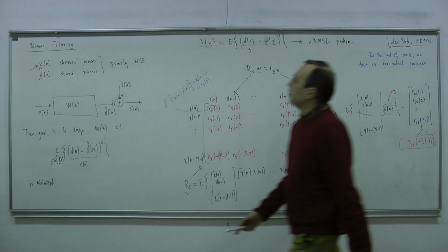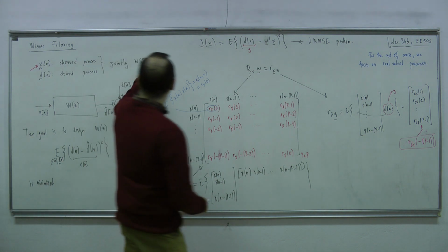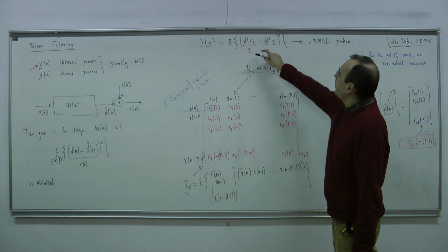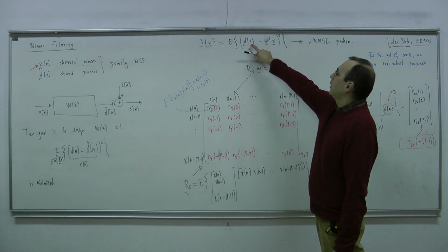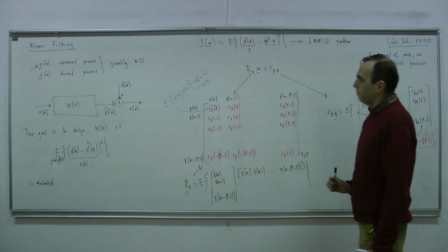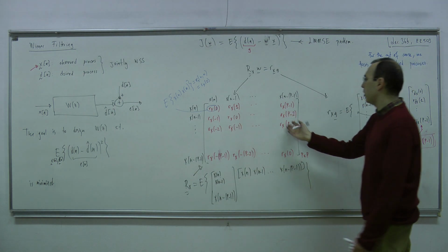Then are we done? If I know X's autocorrelation sequence and their cross-correlation sequence, given that they are jointly wide-sense stationary, I am done. Now here is the case. In this equation system, do you see a dependency on n? In this matrix, for example, do you see any n? I see Rx0, Rx1, etc. So there are no n's.